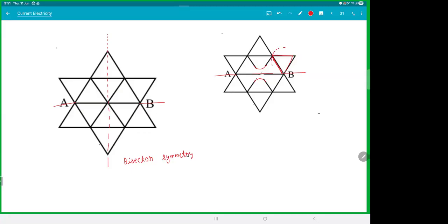So this whole triangle here is 2R by 3. Similarly, this whole triangle here is 2R by 3. And this one is R and R, 2R; R and R, 2R. 2R and R in parallel, and R and R is again R by 2. So this middle section here is R by 2. Same logic here. This guy was 2R by 3. This middle one is R by 2. You can fold it, but okay, I'll leave it like this. This is 2R by 3.